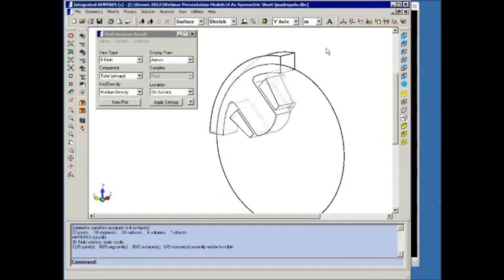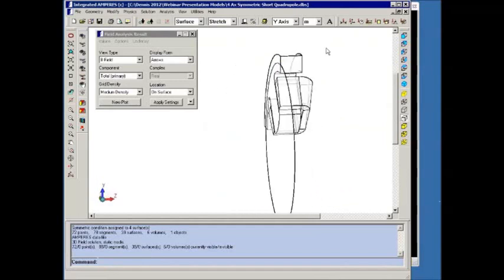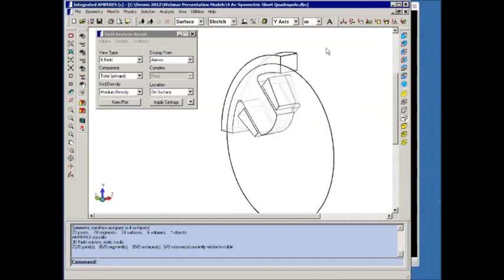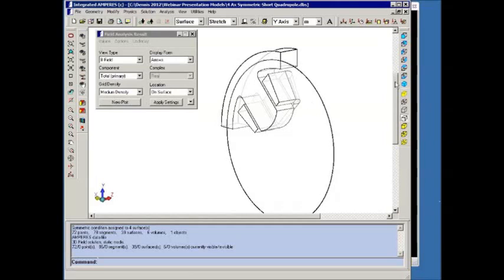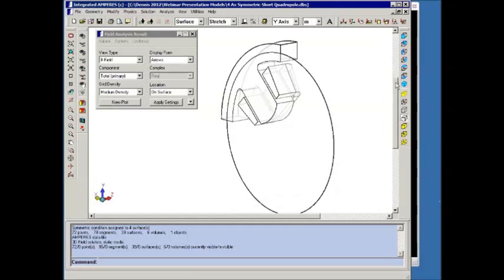Now, if you're familiar, as I'm sure you are, with our modeling rules, normally we don't allow overlapping surfaces. When you have two objects that are touching each other and their two surfaces are touching, that's generally not allowed. But again, there's no physical substance to the plotting circle. It's just there for convenience. So that causes no problem, even though it's overlapping part of the pole and part of the coils. Because there are no physical properties, it doesn't interfere with the field solution at all.